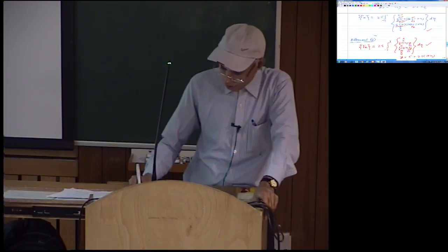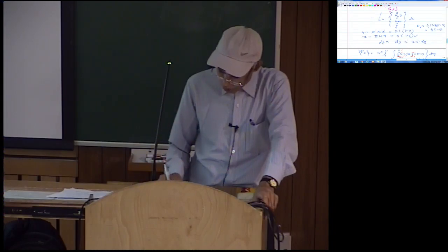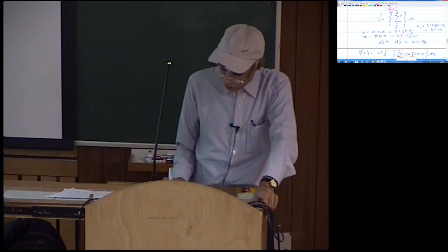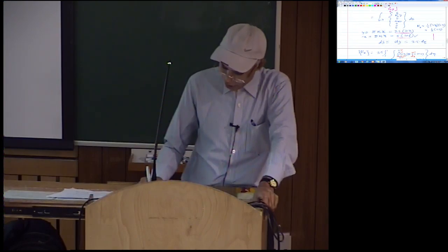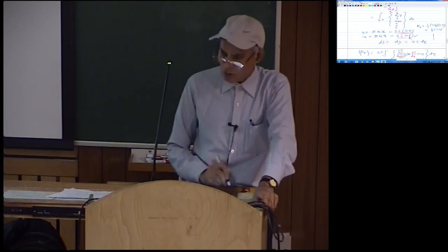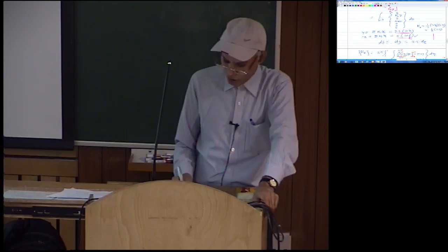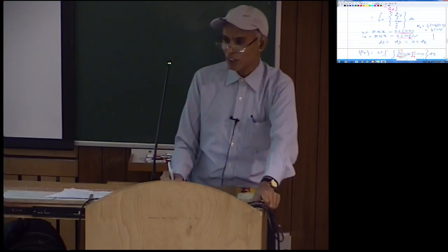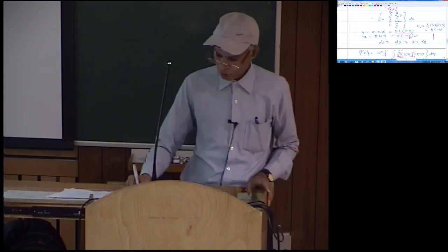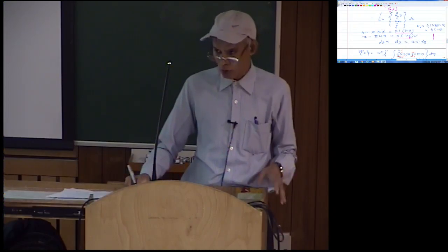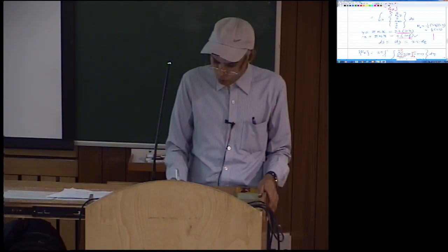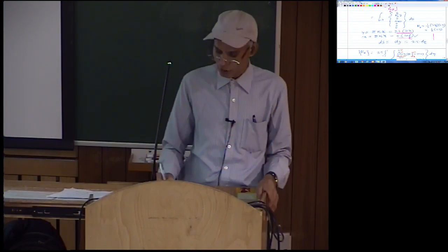That is coming from here. So as I said, expression for y is this, expression for x is this. You are going along this edge where your xi coordinate is constant. So x is constant, so dx is 0. So then ds is only square root of dx square plus dy square, which is just dy, because dx is 0. So the square root of dy square is simply dy, and then dy is from this 2.5 into d eta if you differentiate this.